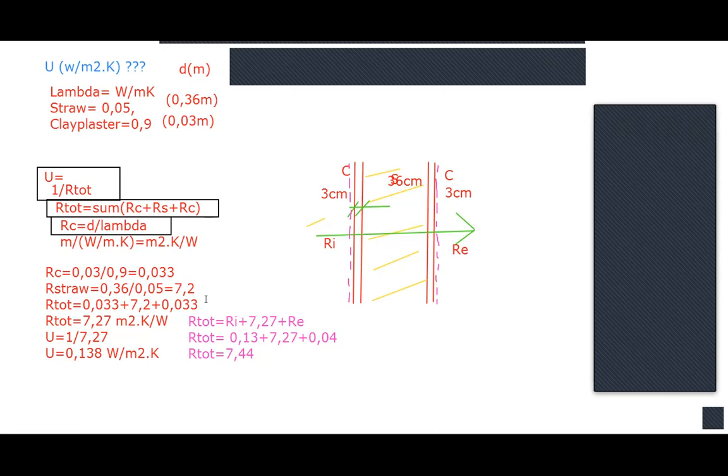And when it's a wall, I think it's obvious. Regarding the roof, it's the 45 degrees rule. If the roof is steeper than 45 degrees, then it's like a wall, and you calculate the horizontal number. But when it's, for example, a flat roof or some roof with a slope up to 45 degrees, you calculate the heat transfer going up.